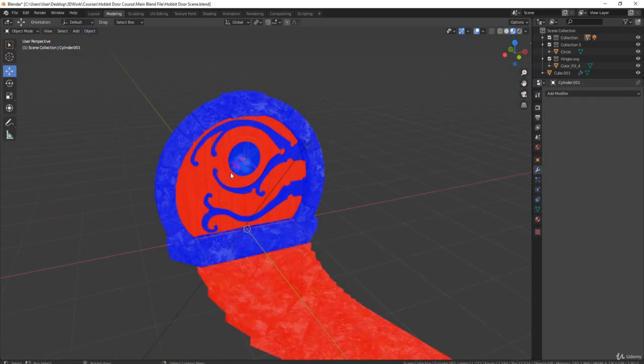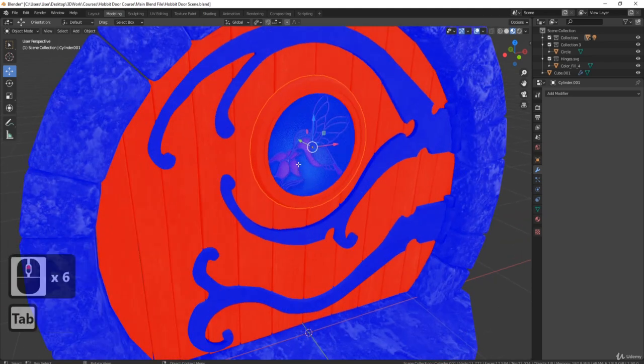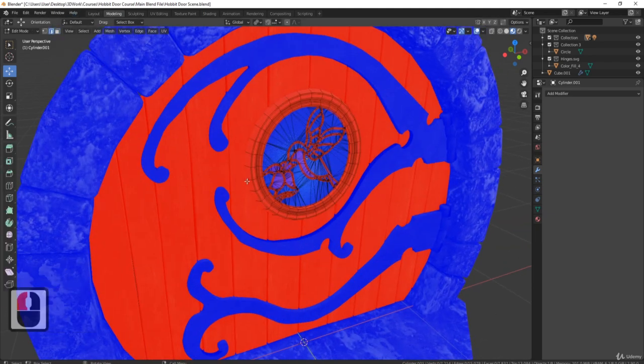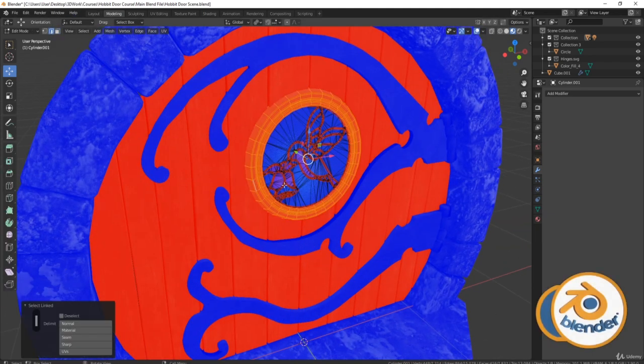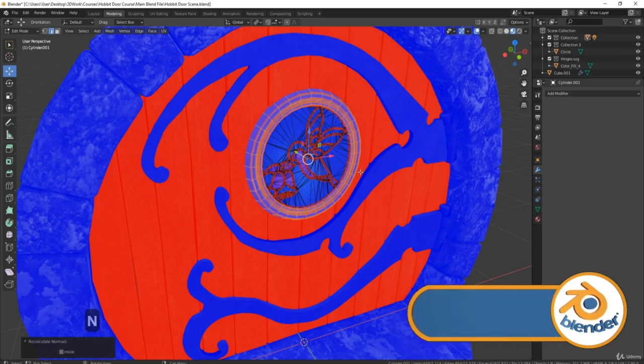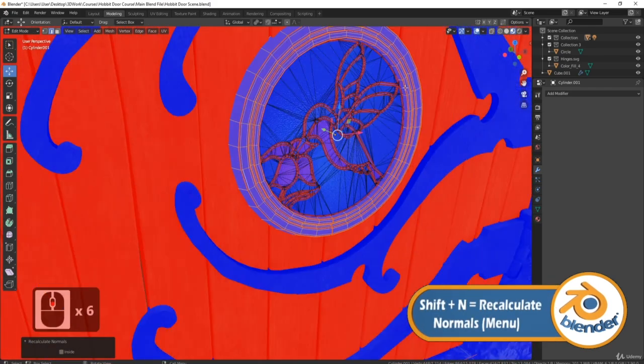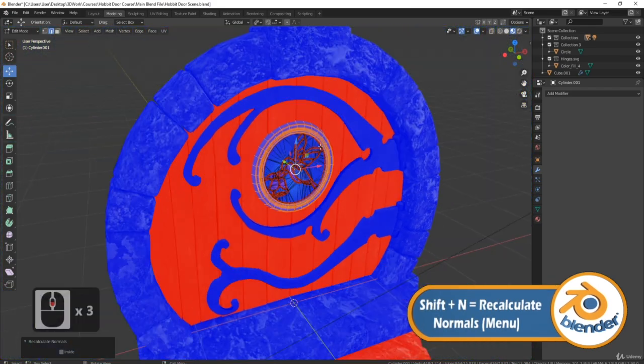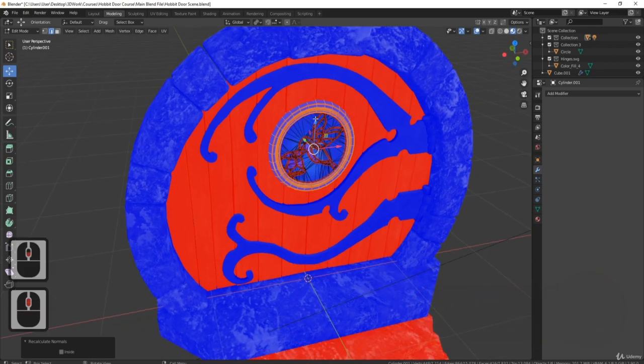So let's now click on our rim first, and we'll do that one first. So we're going to come in, we're going to make sure we're on edge select. I'm going to grab the whole of the rim, like so, Shift N, and spin that round. Now I'm just looking to make sure none of the glass or this metal part is the same, and I think I'm happy with that now.